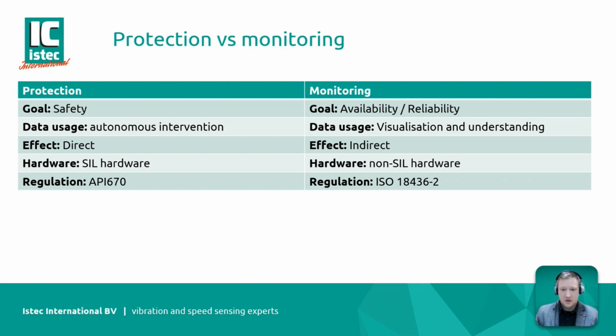As I mentioned, in the past a lot of systems had a physical disconnect between the protection and the monitoring side. If you had a rack-based system with different cards, the condition monitoring and the protection were done on different cards, where the protection cards were completely isolated.